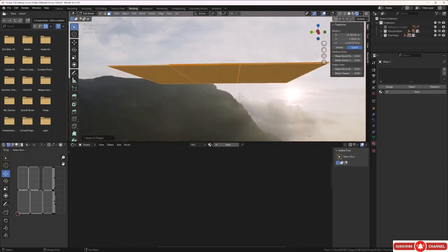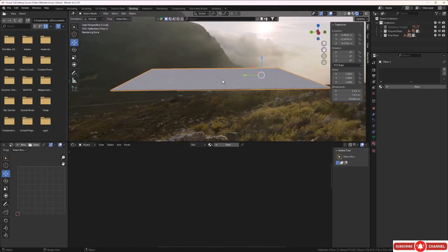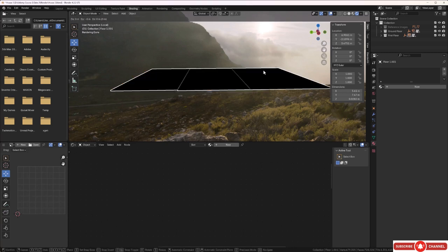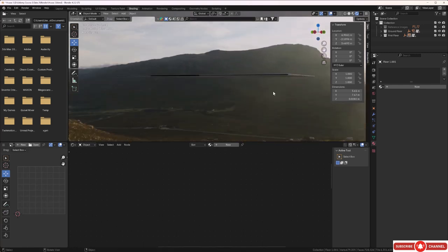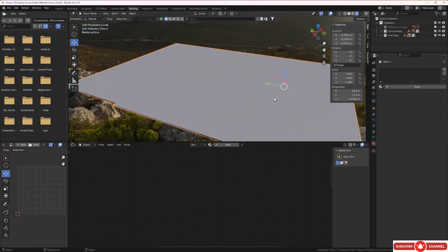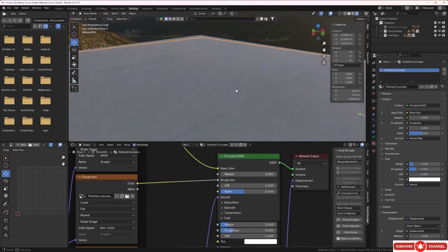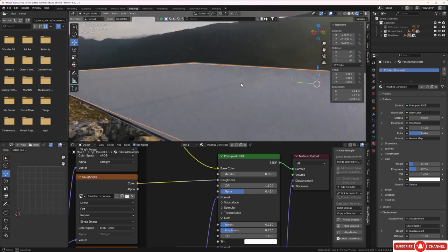Okay, so what we maybe do straight away now is let's tap out of edit mode, grab this one, and then we'll press Shift D, and we'll press G and Z, and take that down just a tiny bit to about there, like that. So again, we've got the two layers on that. Alright, let's grab the top layer, and let's hit the plus key, and we'll hit the drop down here, and we'll type in polished concrete. And there it is, and we'll select that and see what we get. And there we go. So the scale we'll leave alone. The settings are all correct now.